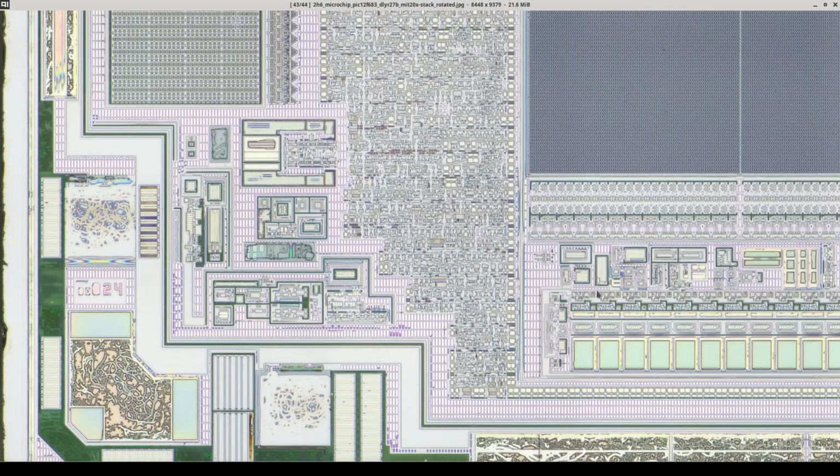And so the way that a lot of the earlier generation PICs with UV erasable EEPROM worked is they did not have an internal charge pump for high voltage generation because you had to use a dedicated UV box to erase them anyway. And so to program these, you would have to apply an external 12-volt power source from the programming device, and that would be used directly as the VPP for the EEPROM.